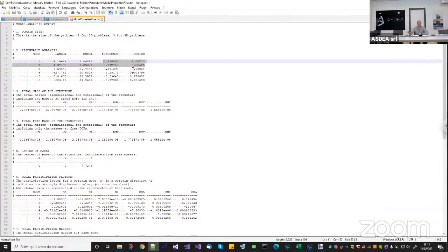produces, because not every element or not every material is implemented in such a way that it gives you an exact tangent stiffness. Sometimes they just give you a secant stiffness, sometimes they can give you an initial stiffness. It does not change the results, but if you use that stiffness for the eigenvalue analysis, it is going to change the result. So always pay attention to that.